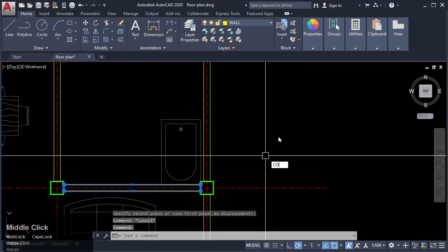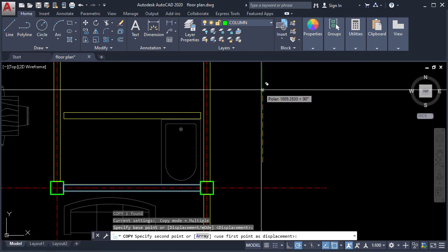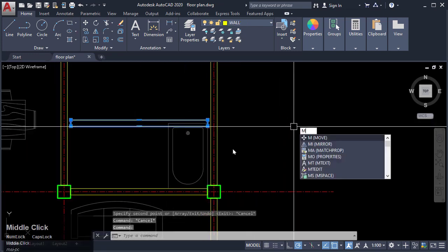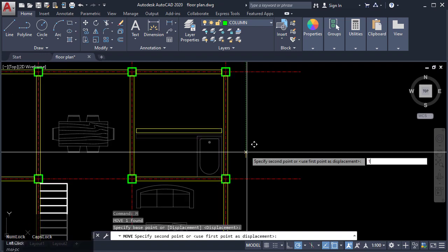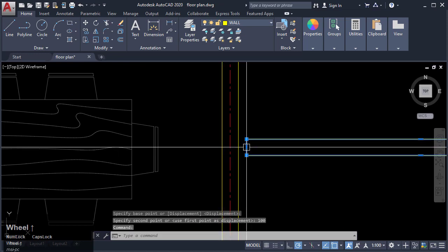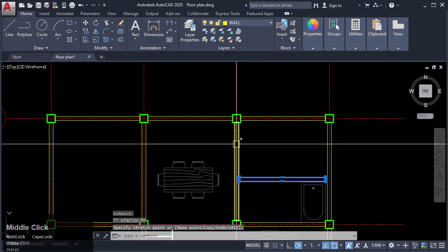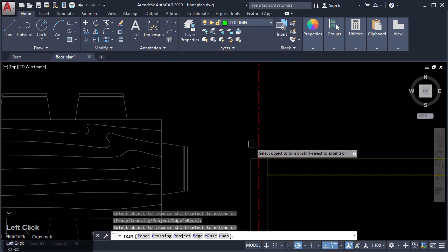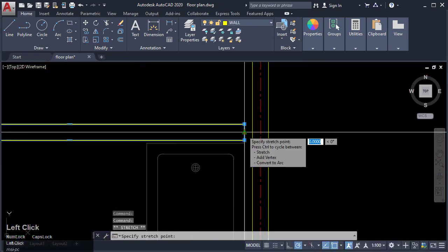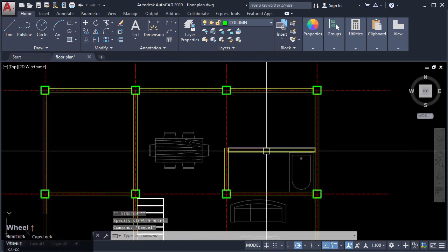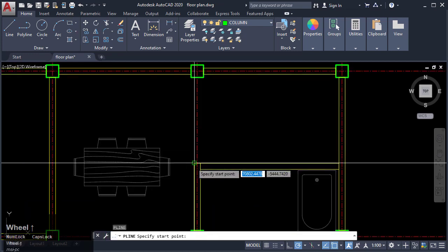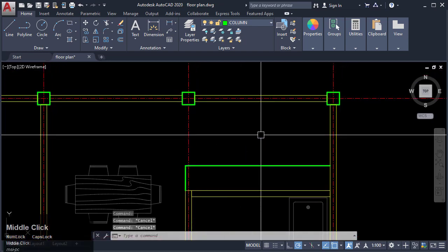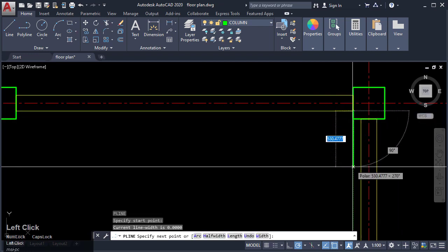And now create a partition wall. Type in the distance, let's say 1,600. Move a little bit further, an additional 100. Stretch the walls to fit the layout of your new floor plan. I will now convert this one into a kitchen. So a typical kitchen has a width of 600 millimeter. So 600. Then same is true on the other side of the wall. 600.